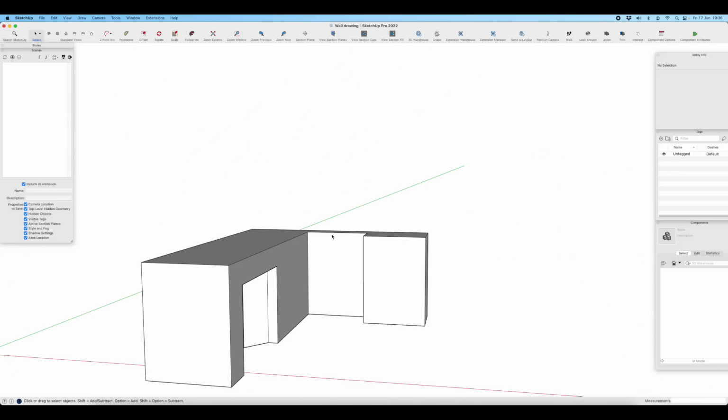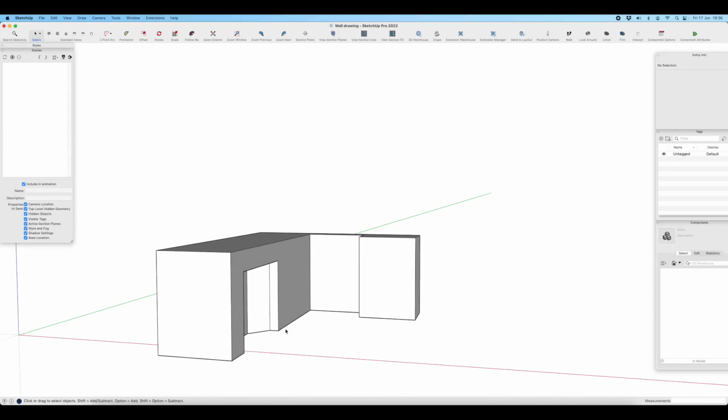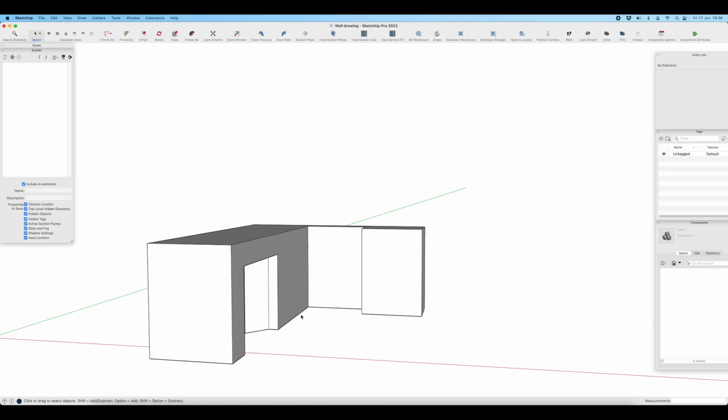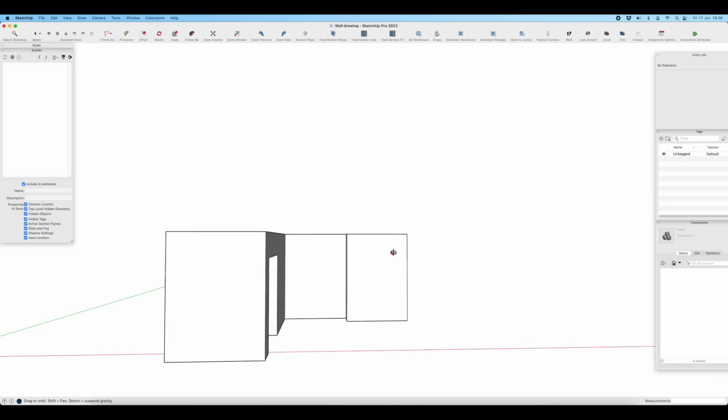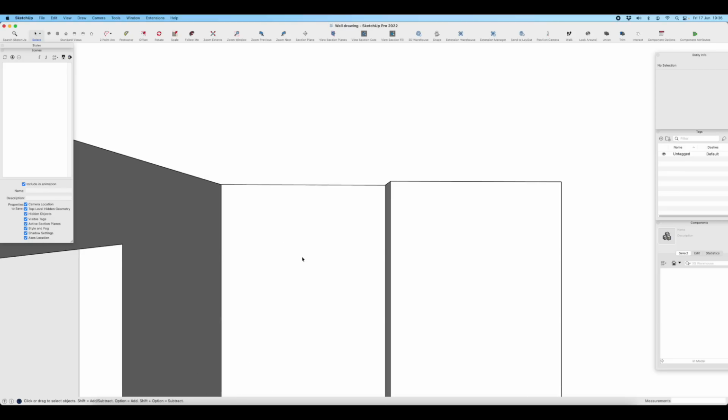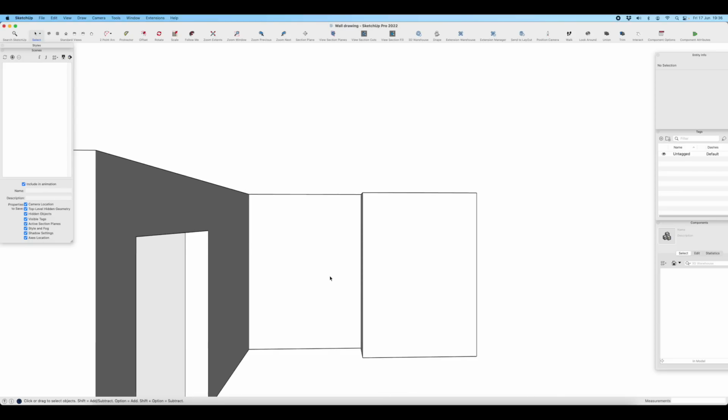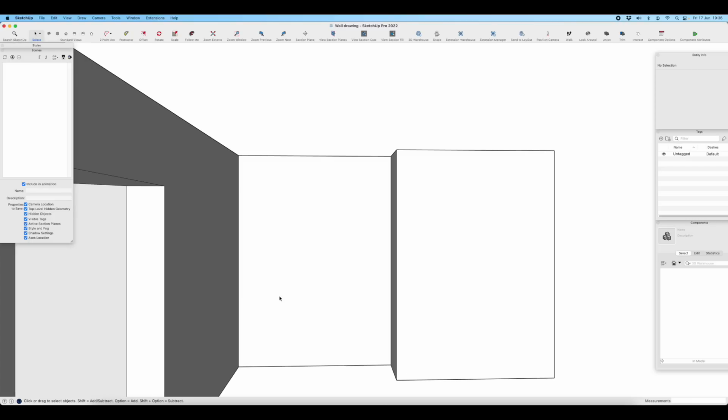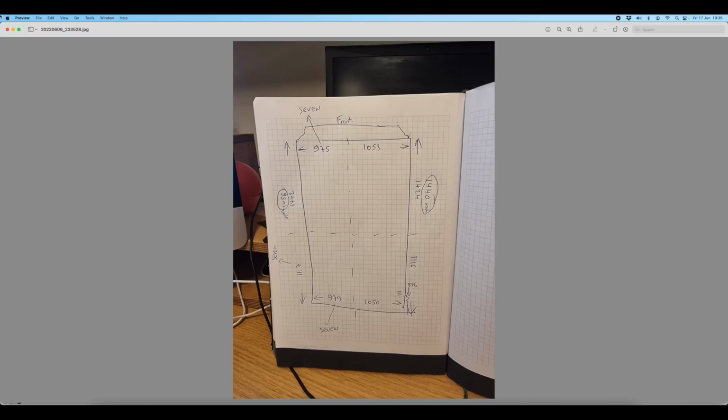We can now go back to the detail from our laser measuring. So we positioned our laser here and cast it at this wall nice and square, and we can use their measurements now to do an accurate drawing of this bit of the wall, so we can get an accurate model and take dimensions off that to make it from. So looking at our measurements, we had out of level top to the frame, so we've got 1442 on the left which we've drawn in and 1424 on the right.